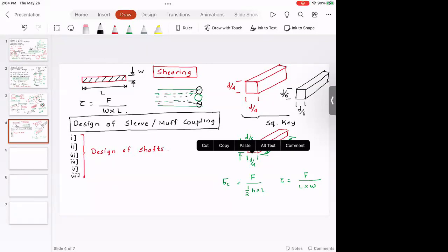The same thing happens with stress concentration. Stress lines are usually uniform, but if there is a sudden obstruction, maybe a hole or an impurity or a sudden change in the cross section, that will disrupt the stress lines, and those stress lines would get accumulated or concentrated in that small region, which increases the magnitude of the stress locally. That is stress concentration in a nutshell.